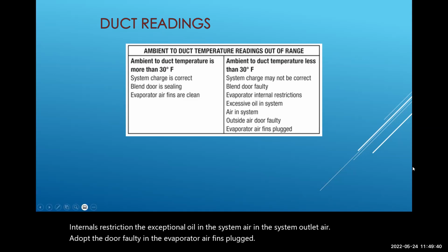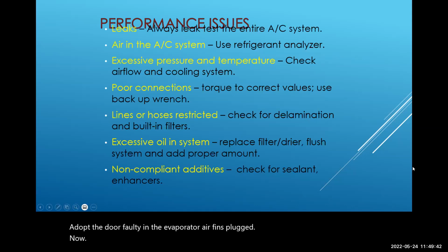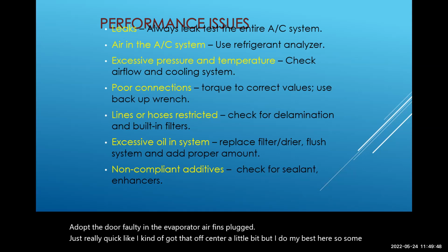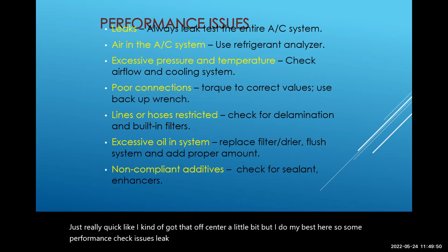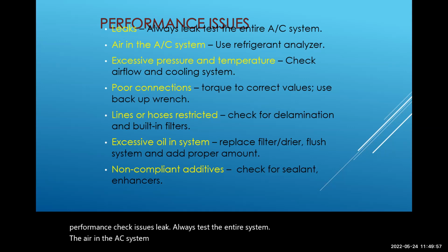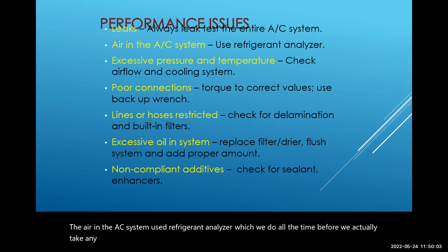Now, just really quick, I kind of got that off center a little bit, but I do my best here. So, some performance check issues. Leak: always test the entire system. Air in the AC system: use a refrigerant analyzer, which we do all the time before we take any refrigerant out. Excessive pressure and temperature: check for airflow and the cooling system.